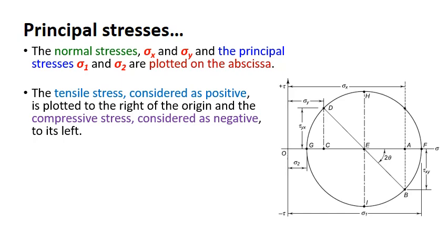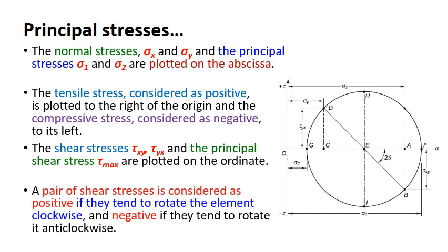What about the sign convention for shear stress? See, if the pair of shear stress rotate the element in the clockwise direction, it is positive. Otherwise, it is negative. So please remember, clockwise rotation is positive and anti-clockwise rotation is negative.